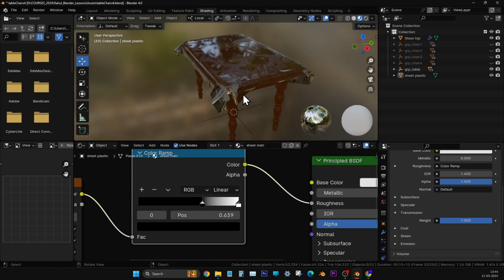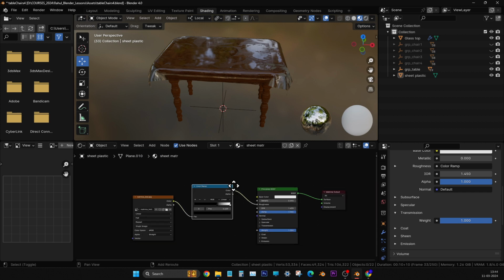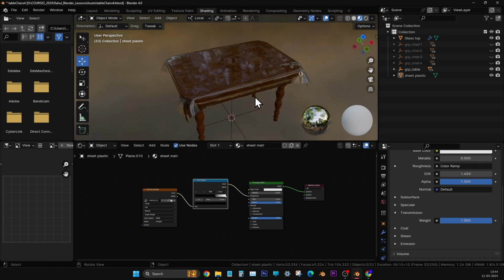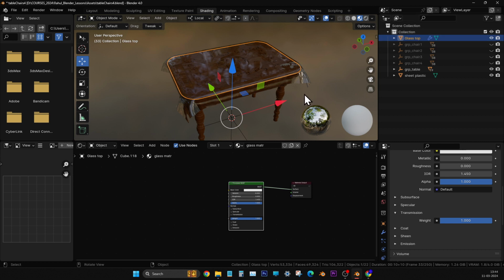Now this one is done, and now okay, we can do this. So what all we did is, first we did the glass top and then applied transparency. Then we created the glass top out of a curve, selecting the edges of the tabletop and then shift duplicating, separating it, then extruding it.